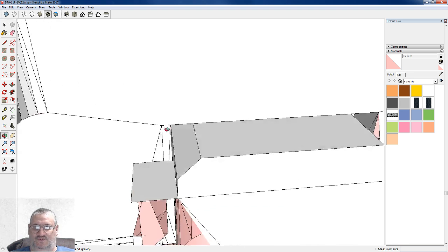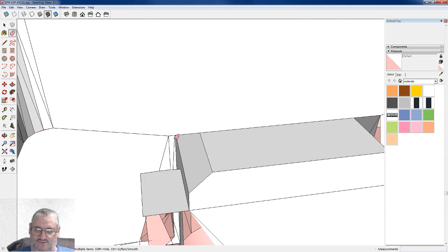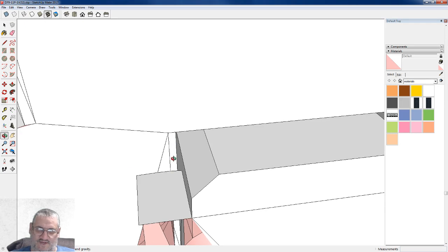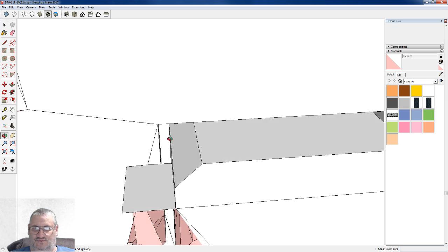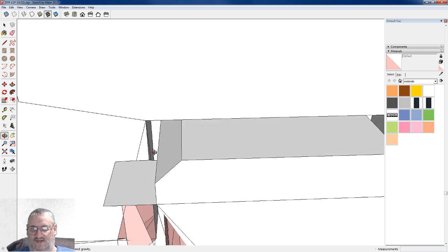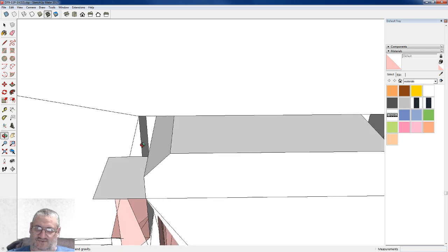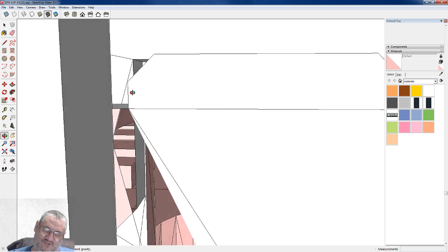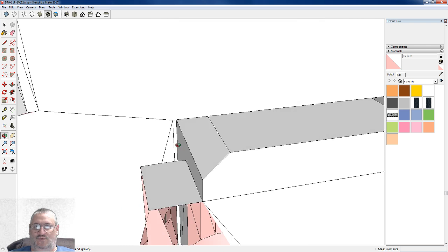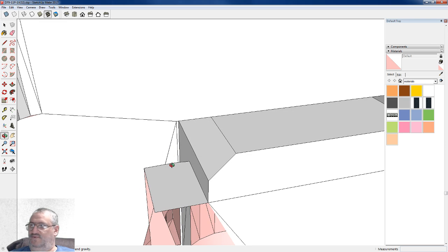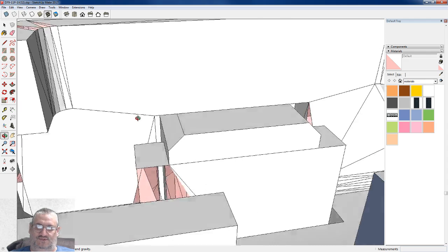So I got most of that. There's still a surface. Okay, there's the back surface. I can get that line. And what that is, you have a square surface back there, rectangular if you will. And then because your CAD systems that this came from like to use triangles, there'll be a diagonal line through it. And you'll see a lot of that. And as long as the rectangle is actually intact, I can delete those diagonals without any problem. If, however, the rectangle is not properly intact, then you get deleted sides.